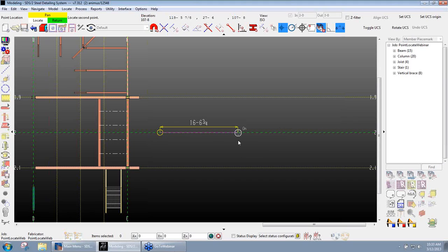Another thing we're going to notice is, next to my point locator here, I have a little indication that at this point in time just says on. That indicates what is actually being snapped to. In this case, it's online. When we start using more point locators, that indication is going to change and show different things based on what point location is being selected.